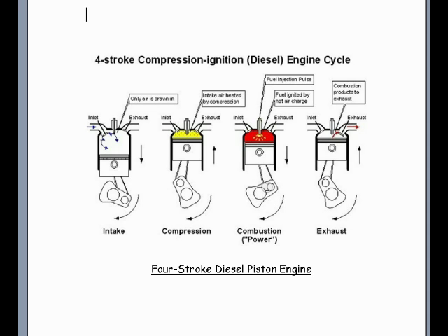Therefore, the torque and the brake horsepower are much higher at lower RPMs. This makes the diesel 4-stroke piston engine ideal for semi trucks and high payload vehicles that require high amounts of torque at low RPM. With the right transmission system, a 4-stroke diesel piston engine can still move a heavy vehicle to high speeds in which very high torque exists at very low RPM.